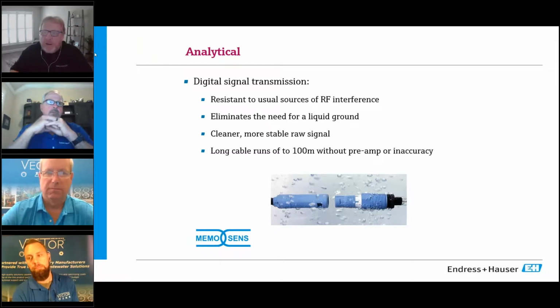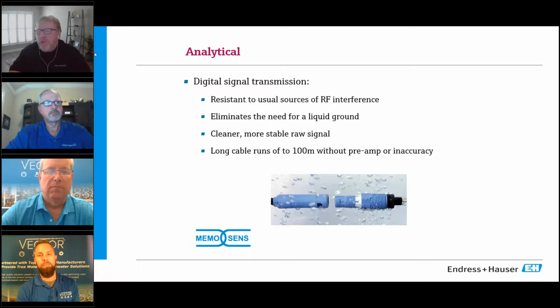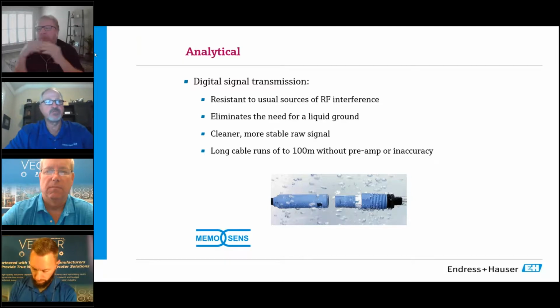So as far as rain, as far as splashing it, as far as cleaning it off under a faucet, none of that is a problem, but you don't want to submerge this below water level permanently because it's not IP68. Yeah, temporary submersion is viable. I mean, again, it's not the connector that's going to fail. It's the glue that holds it to the probe. Yep. Okay, great.